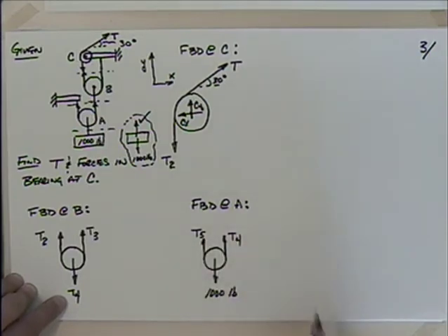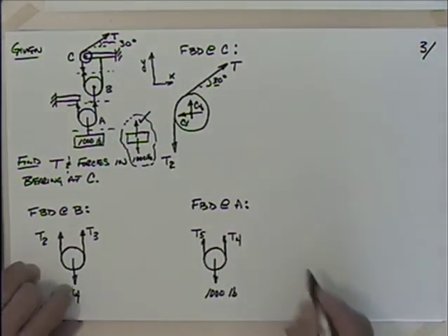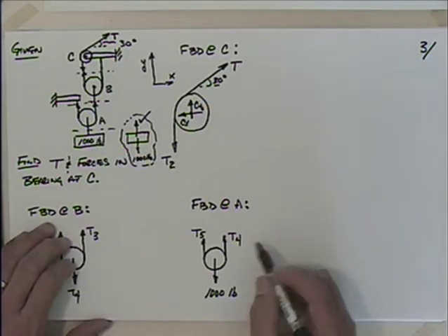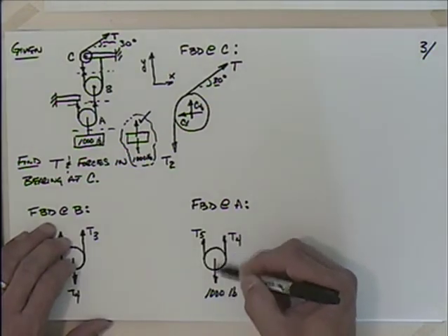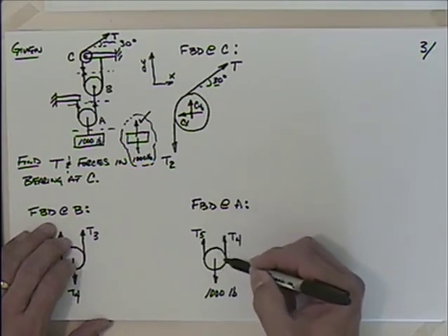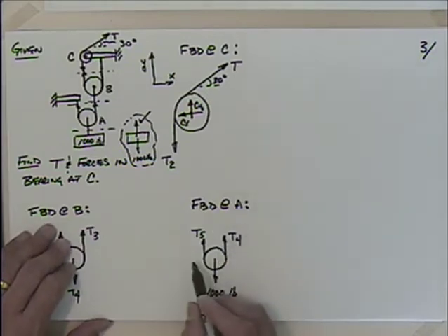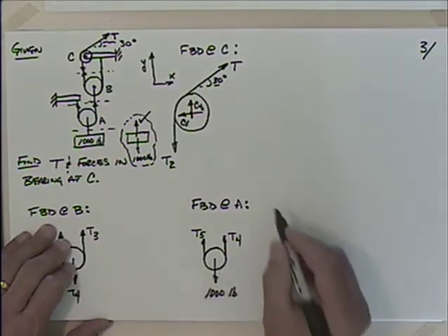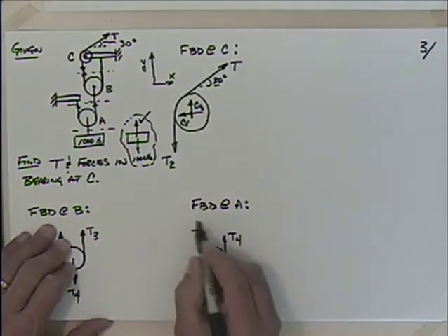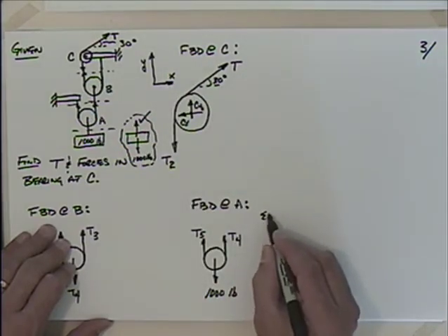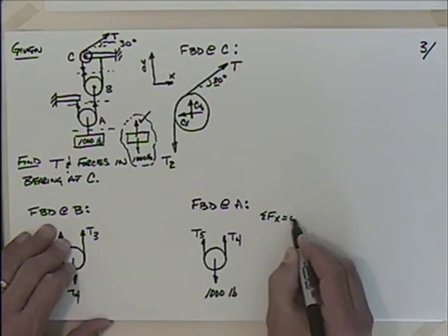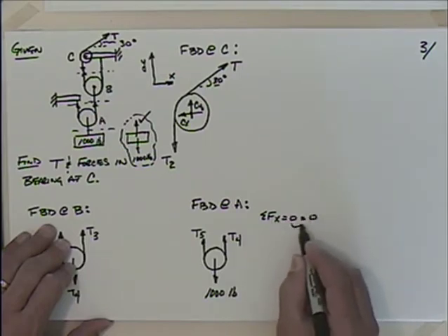Hopefully we don't have to deal with that. So if I go through this then, I've got, again, a parallel situation, so I only have two equations: the sum of the forces in the vertical or the y direction, and the sum of moments. My sum of the forces in the x gives me a trivial equation, 0 equals 0. If I sum the forces in the x direction, setting that equal to 0, I get 0 equals 0. Trivial equation. That doesn't help me very much.